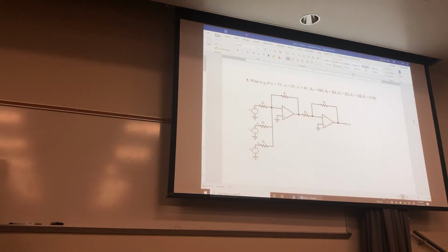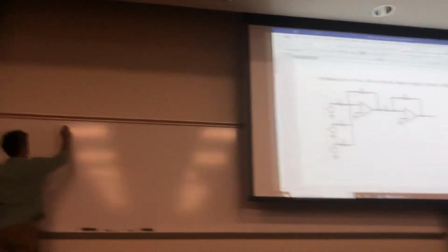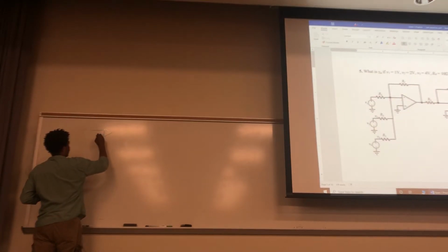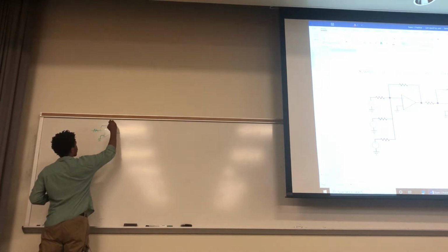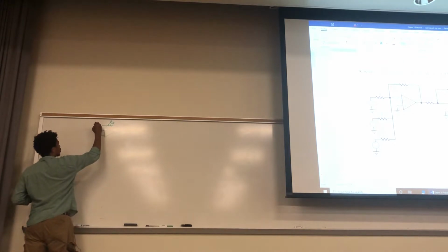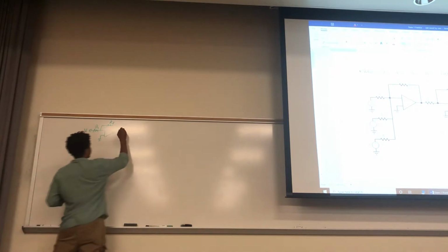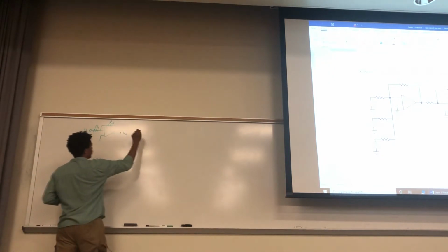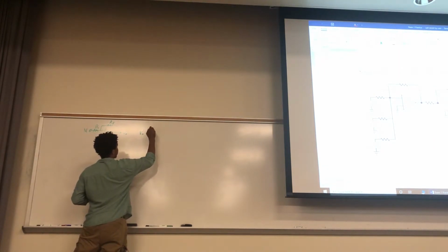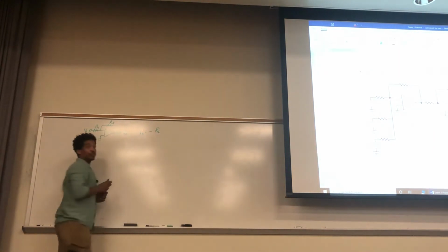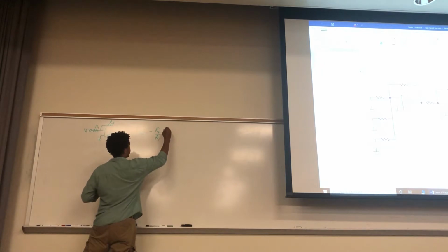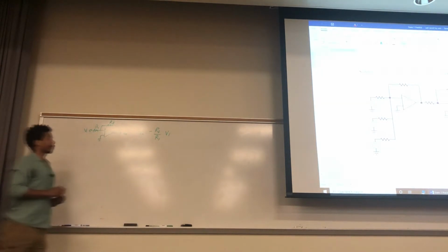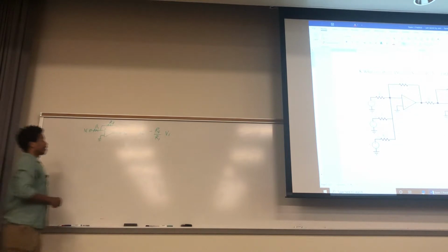Okay, so remember, here's what we know from these types of op amps that look like this, where this is RF. Here's, let's call it R1, and it has some input right there. And here's the output. So we know from these right here that the output is negative RF, RF is on the numerator, over R1 times whatever the input is. So it's like these ratios.